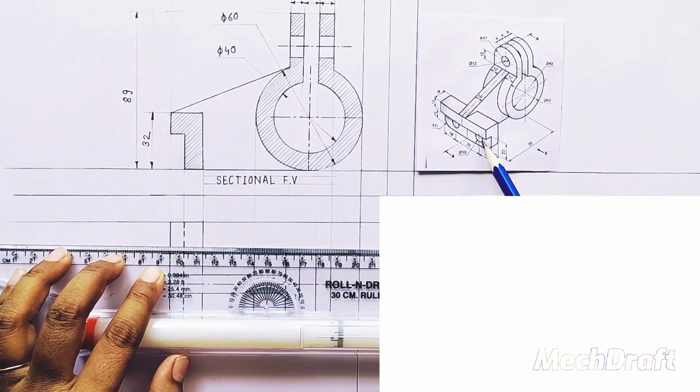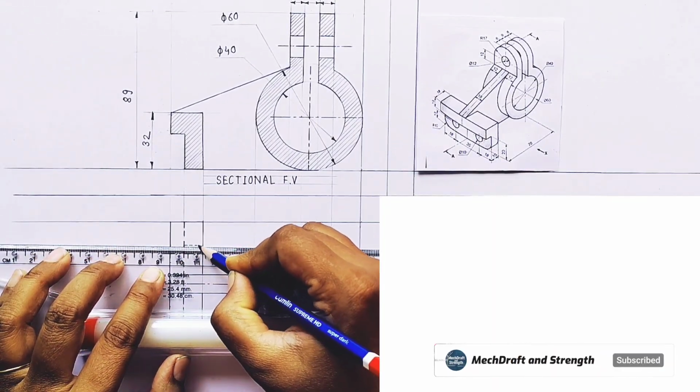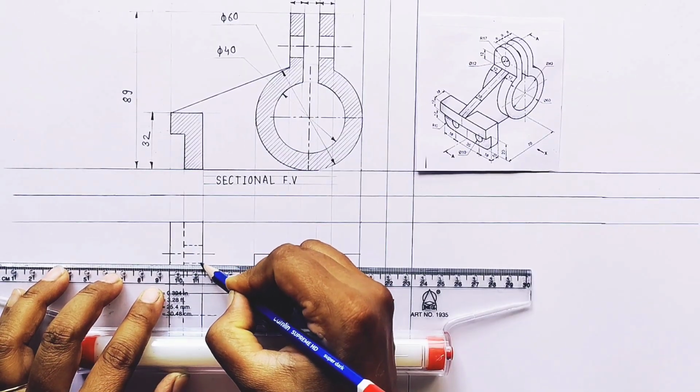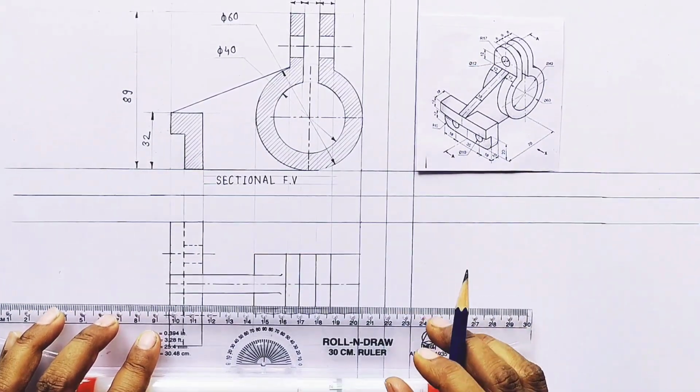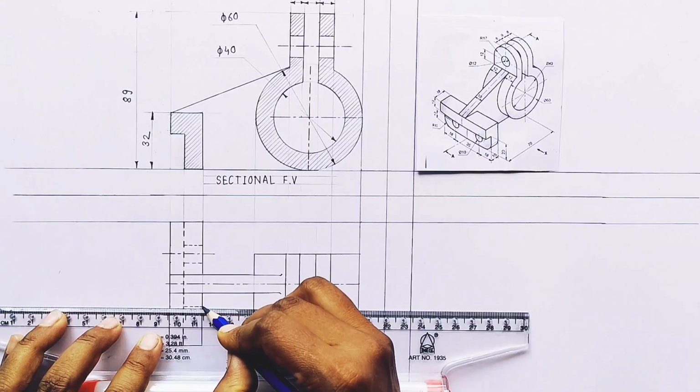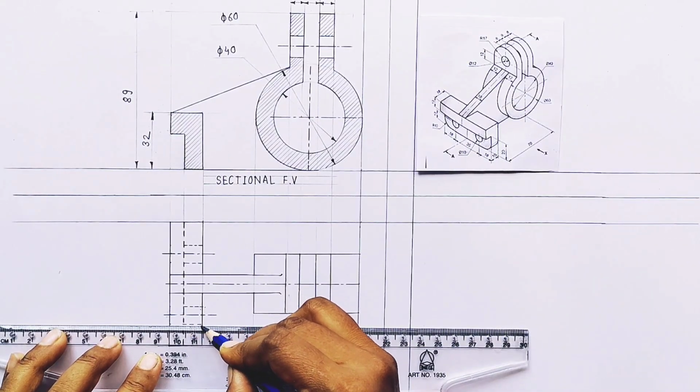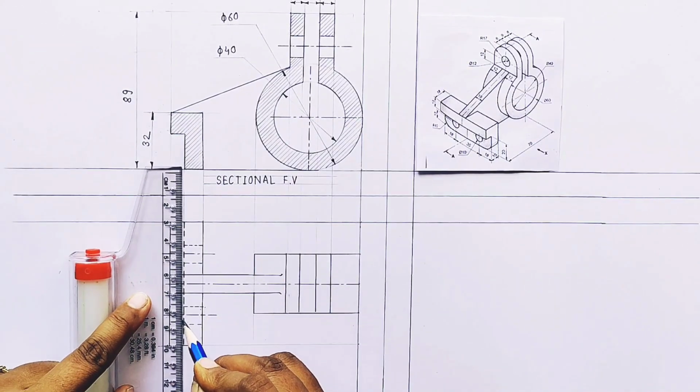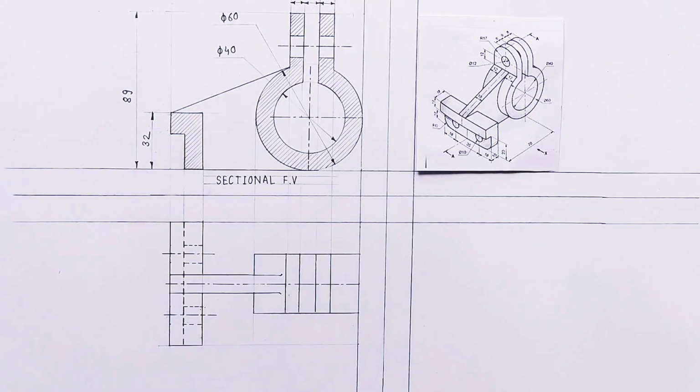You can draw hidden lines in a top view, side view, any view, but in a sectional front view, sectional top view, or sectional side view, you can't draw dotted lines or hidden lines. Okay, then next,